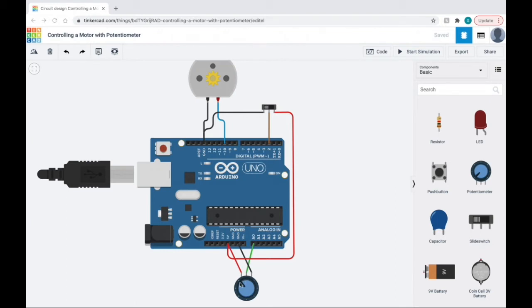It is just a variable resistance where we set the value, and that corresponds to some voltage value, which is called analog because it's not 0 or 5 volts, but any value in between. So we use that input to control our motor, and the Arduino should do some calculations to convert from that voltage value we get from the A0 pin to the rates that we're going to run the motor at.